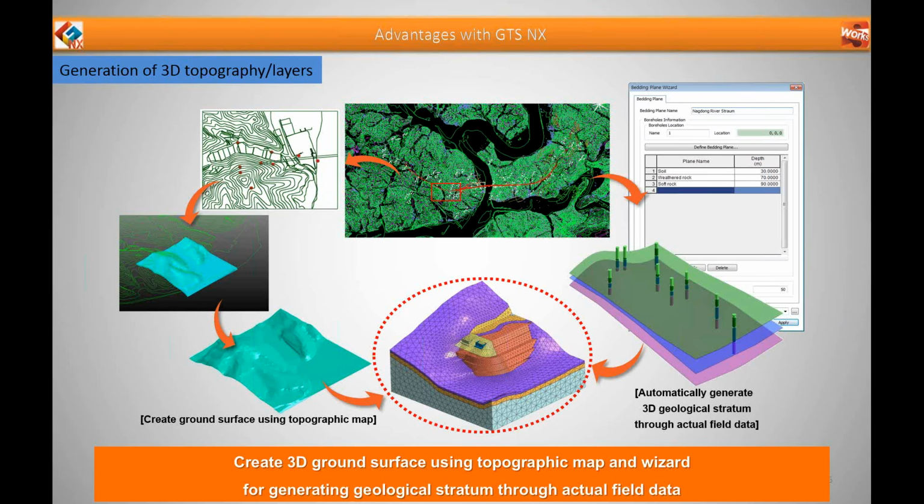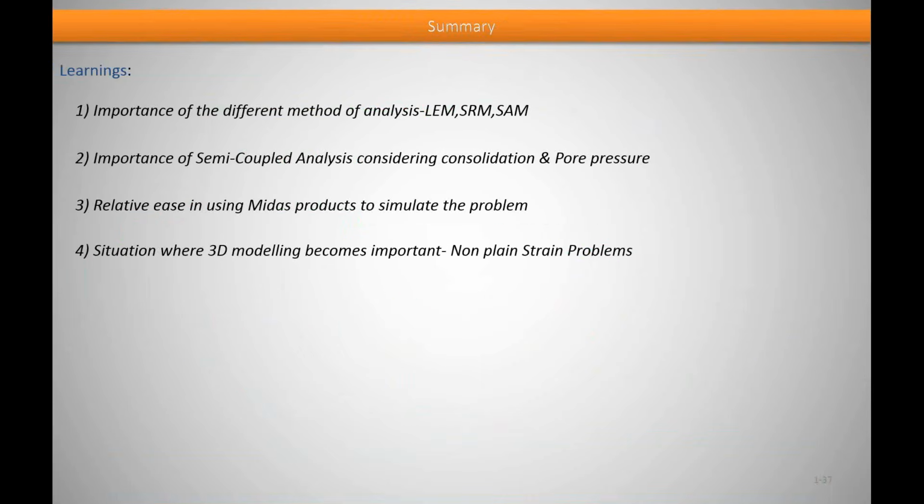So moving on to the presentation. I would just like to summarize what we discussed till today. The learnings from today are the importance of the different methods of analysis, LEM, SRM, SEM, their shortcomings and their effectiveness in various fields. The importance of the semi-coupled analysis, like considering pore pressure, that is the seepage slope analysis, and the consolidation, that is the soft ground slope analysis, and the relative ease in using the MIDAS products to simulate the problem. And also the situation where 3D modeling becomes very important, that is the non-plane strain problems.